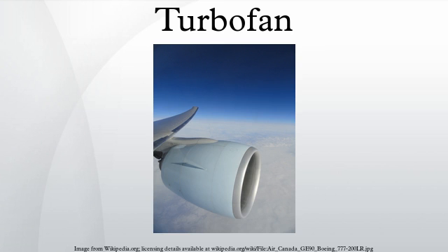slightly away from surge. At higher flight speeds, the ram rise in the intake increases nozzle pressure ratio to the point where the throat becomes choked. Under these circumstances, the throat area dictates the fan match and, being smaller than the exit, pushes the fan working line slightly towards surge. This is not a problem, since fan surge margin is much better at high flight speeds. The off-design behavior of turbofans is illustrated under compressor map and turbine map.